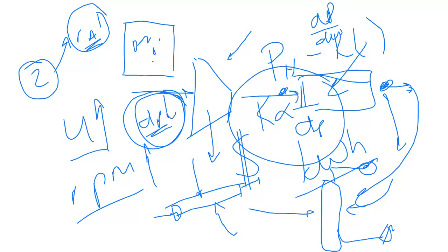But pressure drop, those frictional losses, that is as a result of the second law. And we cannot get past that second law. We have to pay. We have to pay the second law. So whatever I do to increase kc is going to have a negative effect in terms of my pressure drop. The pressure drop will always increase for all the variables.